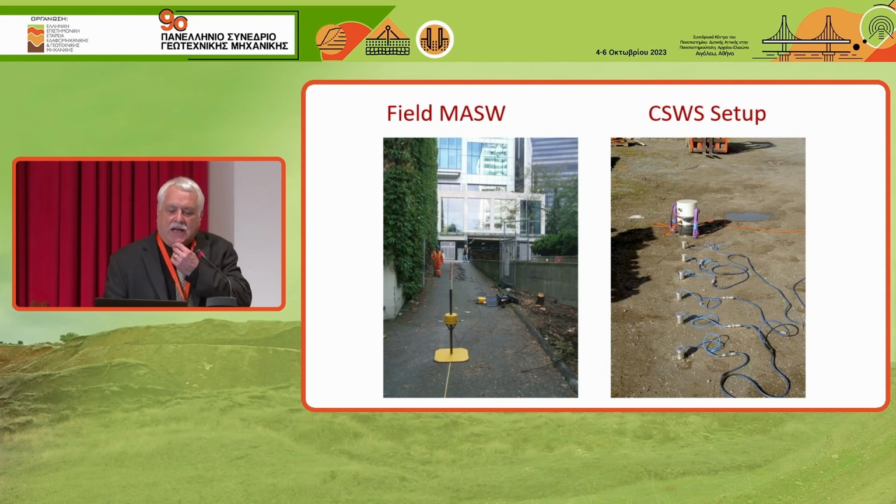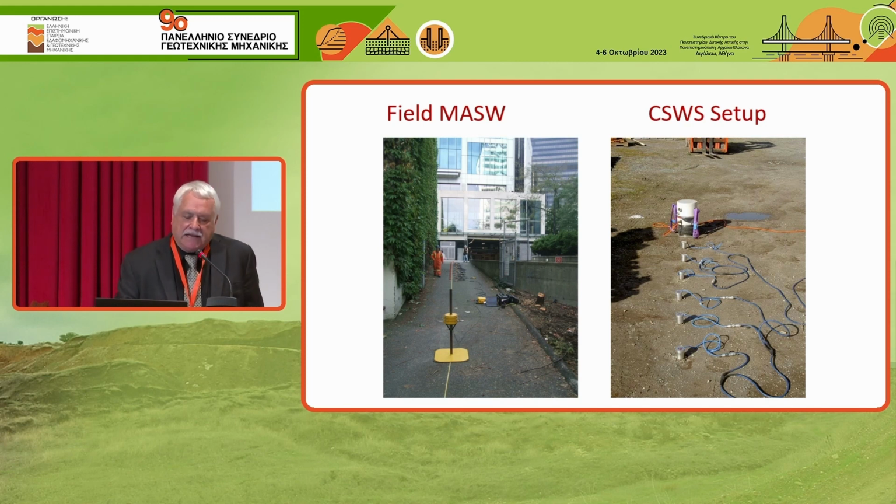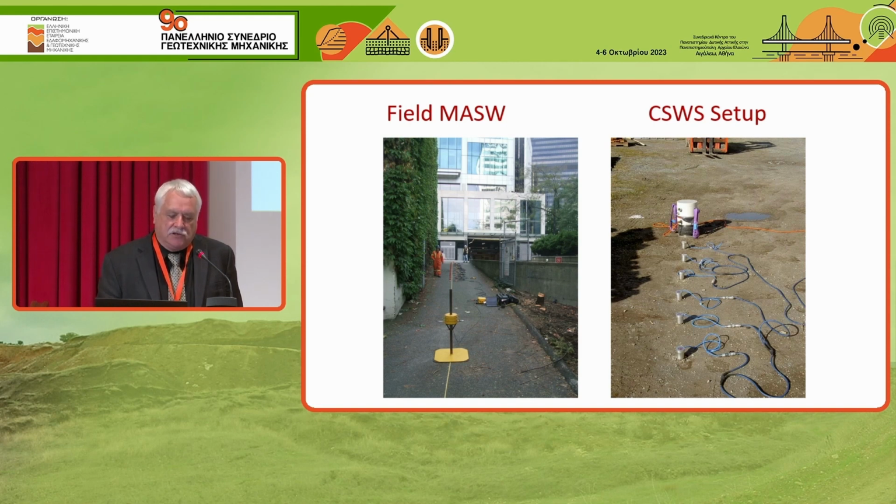On the right-hand side, this is, I think, GDS equipment sells a commercial package for 30,000 euro. You get 6 little geophones on the surface and a little tiny shaker. That shaker's not very big, so I'm not sure you can get down very deep. On the left-hand side is Context system with 24 geophones, and here they're using an impact source. And they can go down pretty deep with that, even through pavements.